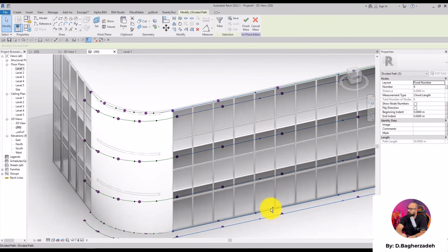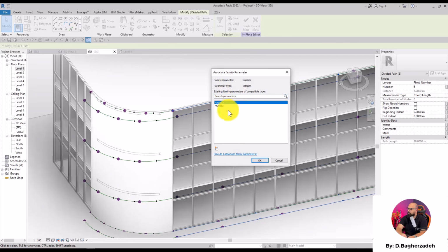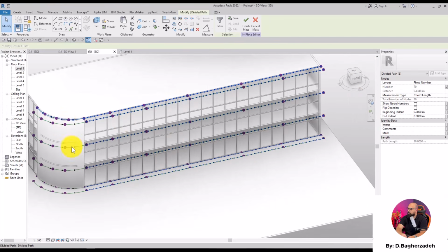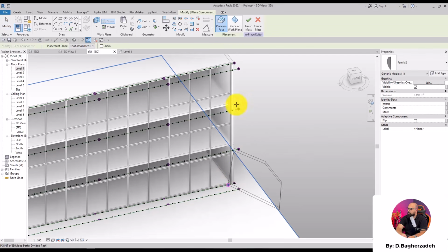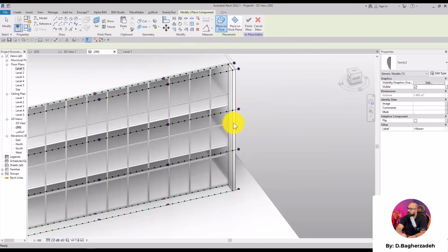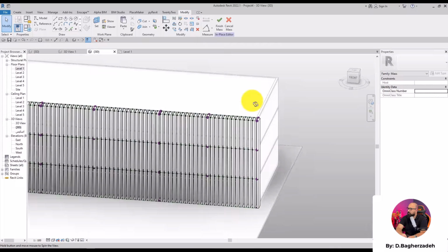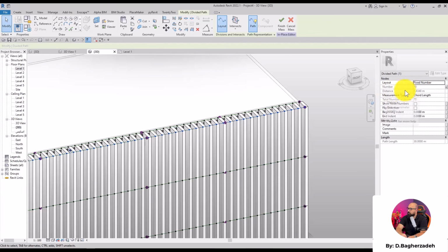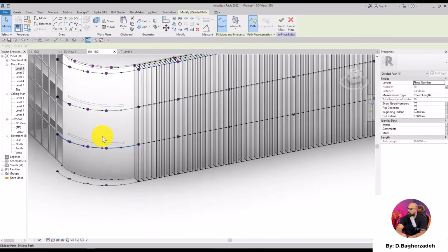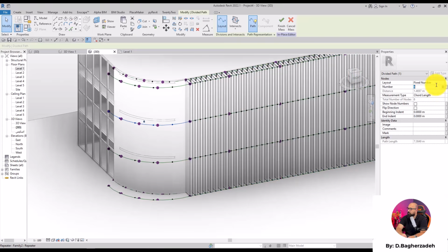Oh, and also, if you want them to work based on this number parameter here, again, the gaps would work quite differently. So, due to all of this, the best thing that we can do here would be setting a single profile here first. And then we can check the gaps to find out whether they work or not. I mean, yeah, this is actually quite nice. Like, approximately, we have a 43 cm of gap in between each profile here. Now, I'm going to start changing this number gradually to find out when exactly we're going to get closer to that 43.